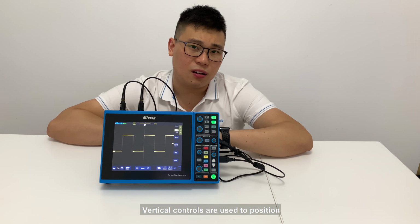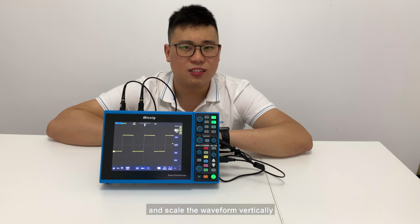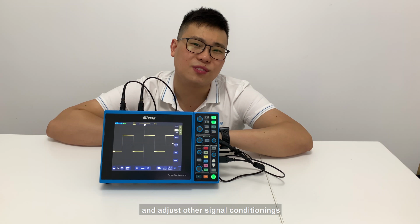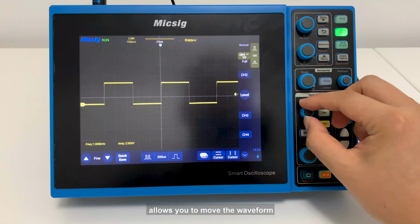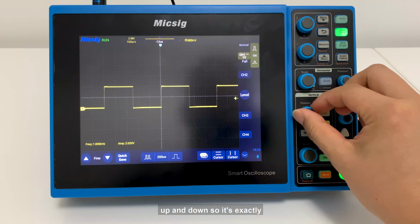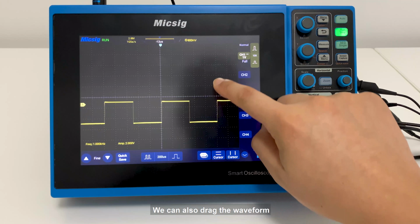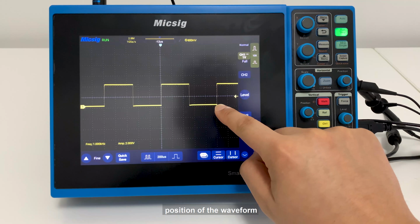Vertical controls are used to position and scale the waveform vertically, set the input coupling, and adjust other signal conditions. The vertical position control allows you to move the waveform up and down, so it's exactly where you want it on the screen. We can also drag the waveform directly to change the vertical position of the waveform.